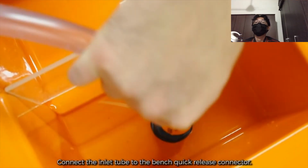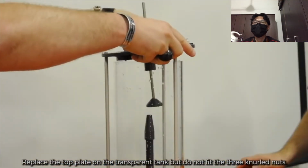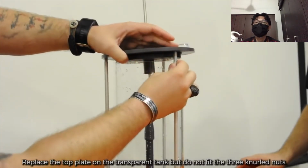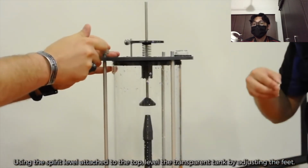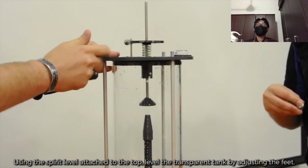Connect the inlet tube to the bench quick release connector. Replace the top plate on the transparent tank but do not fit the 3 knurled nuts. Using the spirit level attached to the top, level the transparent tank by adjusting the feet.